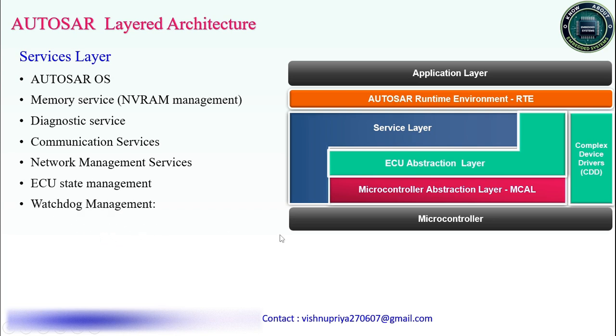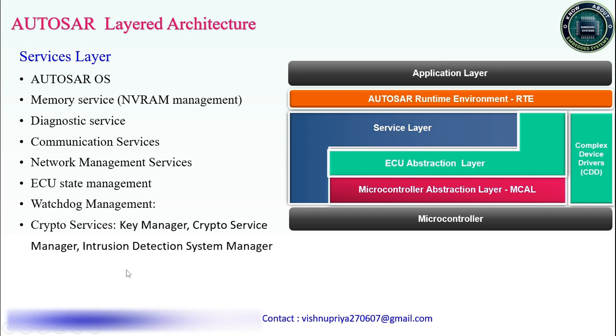Watchdog management. In the microcontroller, we have different watchdog timers, like the system watchdog timer, the external watchdog timer, and different watchdog timers. It covers when the watchdog timer should be triggered, when the watchdog timer reset should happen, and in what situation the watchdog timer should be idle. All these configurations and services will be provided under watchdog management in your service layer.